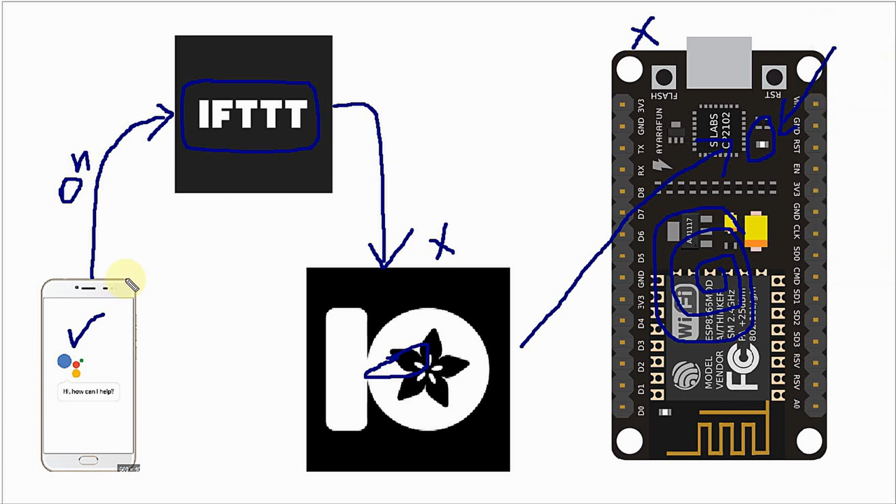Then we will configure another voice command from Google Assistant in IFTTT, that if we receive "off" from Google Assistant, we will provide the MQTT request to the Adafruit IoT platform for toggling the state of the dashboard button to off, so that the state of the LED is controlled via the toggle button in the Adafruit IoT platform, and that program is already running in parallel in ESP8266.